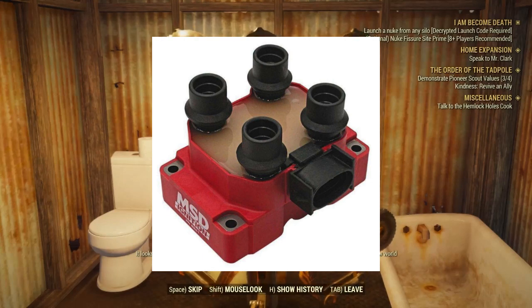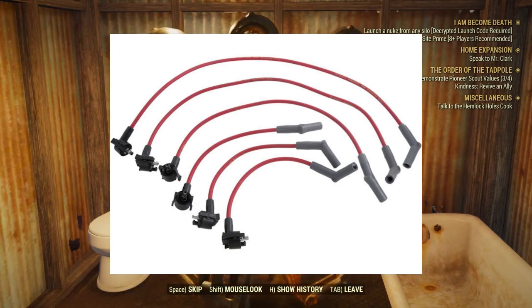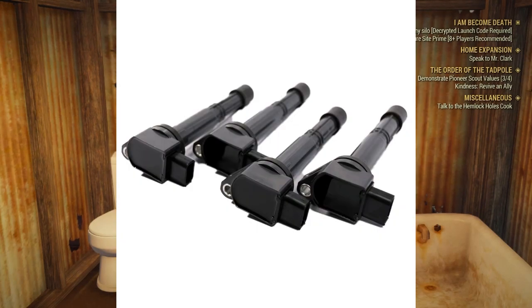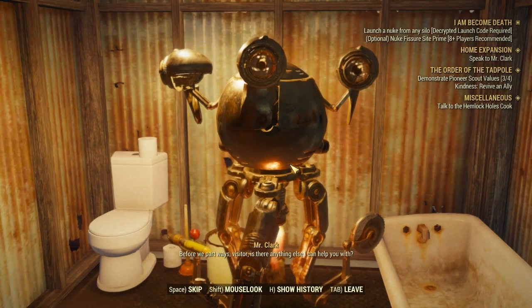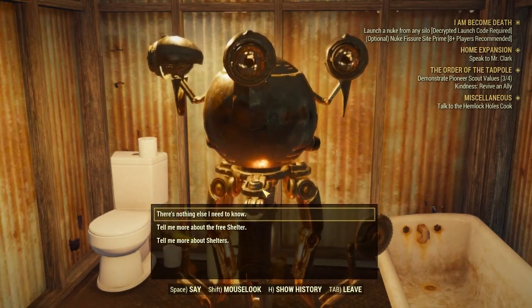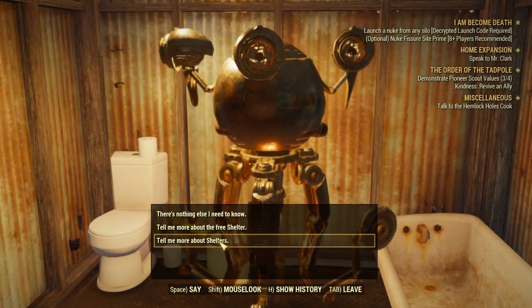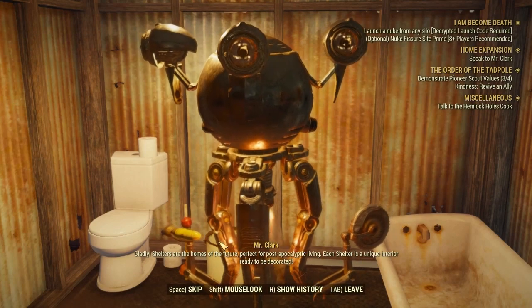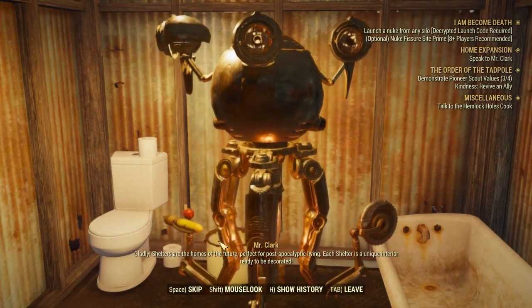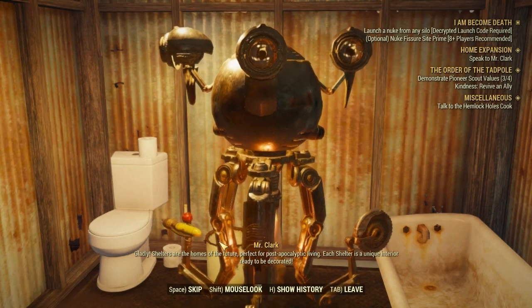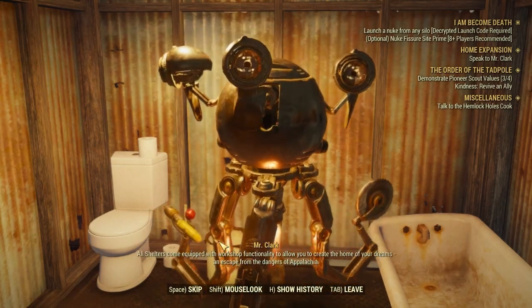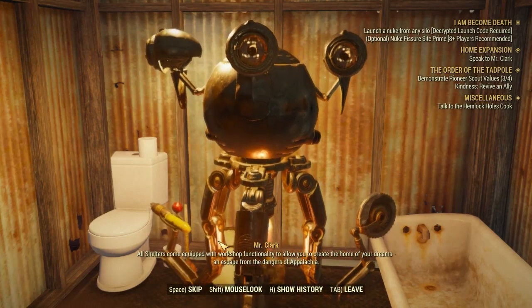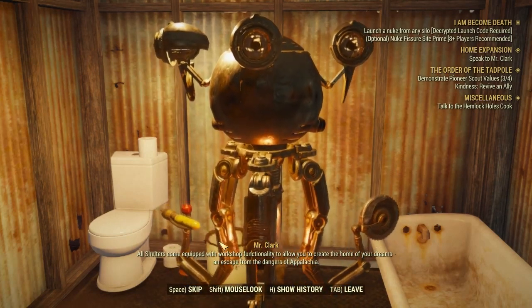It's the same thing as the coil pack, except coil packs usually used wires to get all the way to the spark plug, versus the coil on plug. It just uses a spring and a rubber or plastic sleeve to reach all the way to the spark plug. They're basically the same technology. From there, we have mechanical limiters. A lot of people ask themselves, why can I only reach a certain speed? These days with modern cars, usually that's because the computer is only programmed to go up to X point and